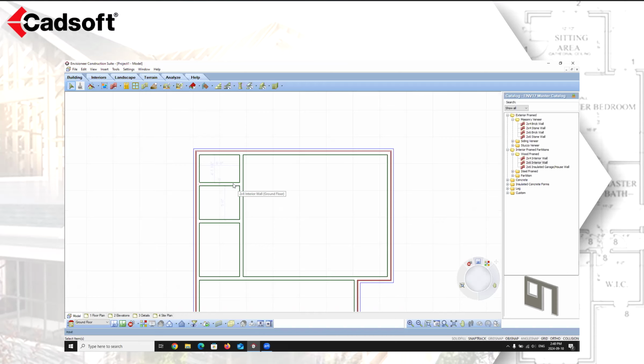A number of different drawing aids are available to help you draw, insert, and edit your elements easily and accurately in Envisioneer. You're always going to want to use the Walls by Baseline tool to create an exterior wall layout with precise dimensions. And you're always going to use the Walls tool to freeform your design or when you're drawing in any interior walls. You're going to use the insertion offset and the duplicate tools to accurately add walls to your model using existing walls or existing points within your plan. So let's take a look at the questions that we had come in.